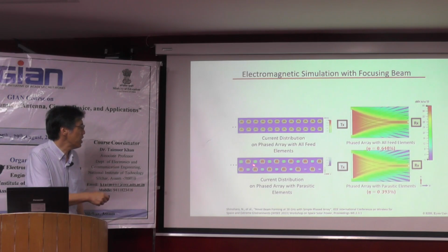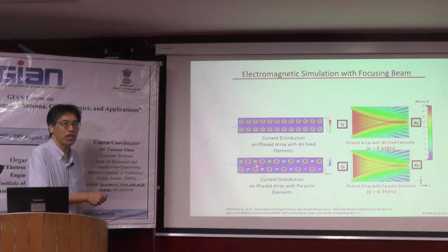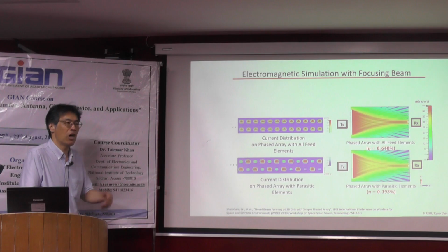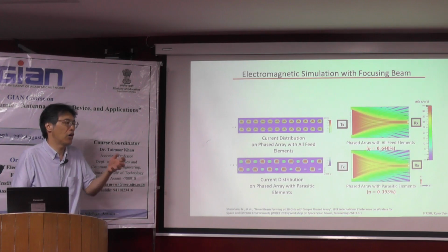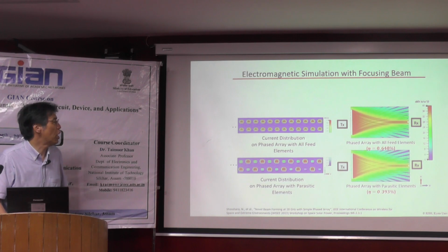And between antennas, we add the metal only, and by the mutual coupling, we create the new antenna here. And as a result, we can create a very similar beamform with half the microwave circuit. So this is our interesting proposal: a new low-cost phased array antenna with a parasitic element.